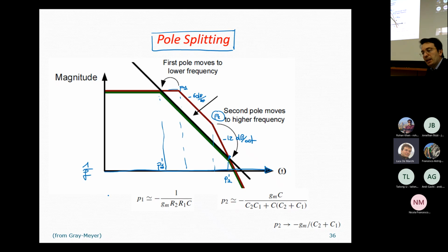So practically no current flows into this transistor after a very rapid transition time. So what we can say is that indeed this node sees I5 entering and I7 sourcing out.